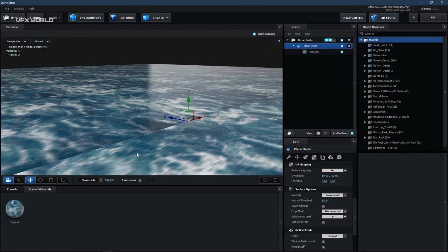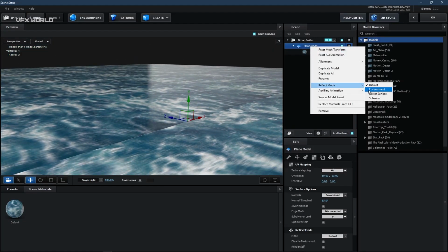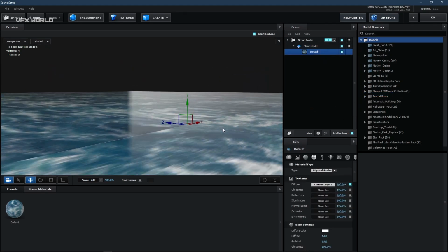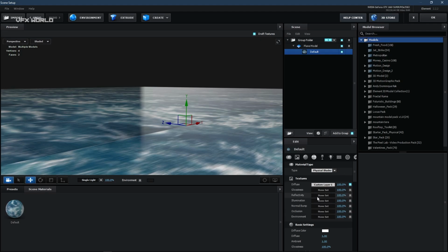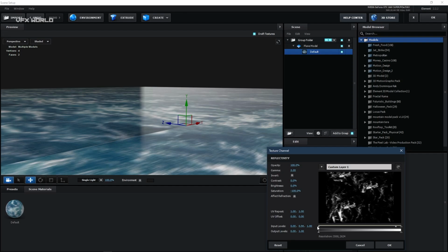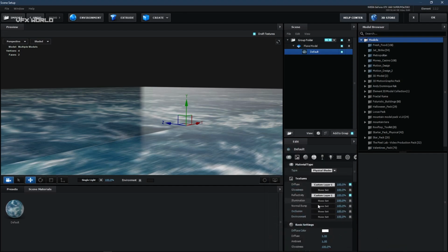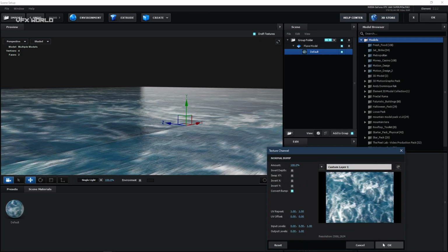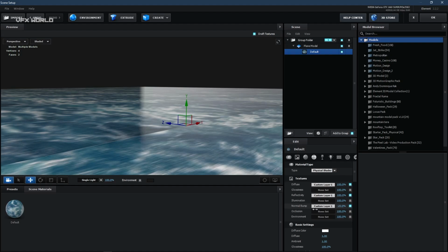Okay, so leave it like that, and after that the reflection mode should be mirror surface, and let's change some settings here. On the reflection panel, first of all I just have to go to the reflectivity and select this one, decrease the saturation down and make some highlighted parts just like this and press OK. And after that, same on the bump map, select this, convert this to a bump and press OK. And now decrease the bump to something around 20%.